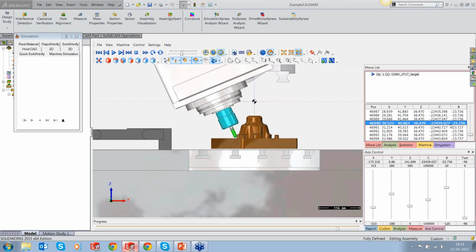In this case, it is not needed. It keeps changing the angle depending on how close the holder is coming to the particular geometry. Right, so very important and very useful feature for mold makers. They can now cut core and cavity, even if it's a big length and if they have a 5-axis machine, they could use shorter tools and run parts on 5-axis by just converting their existing 3-axis tool path to 5-axis. Okay.